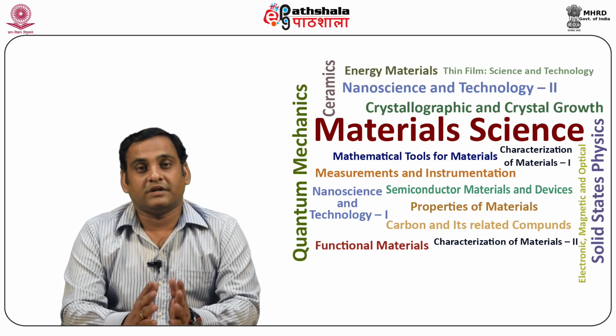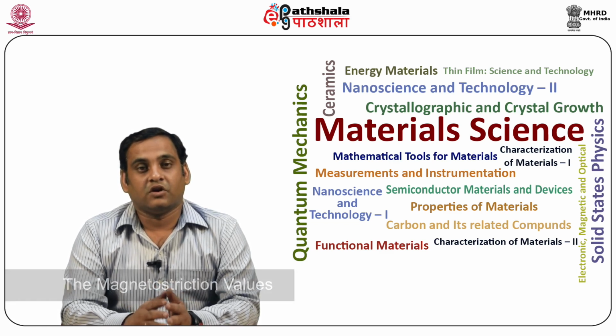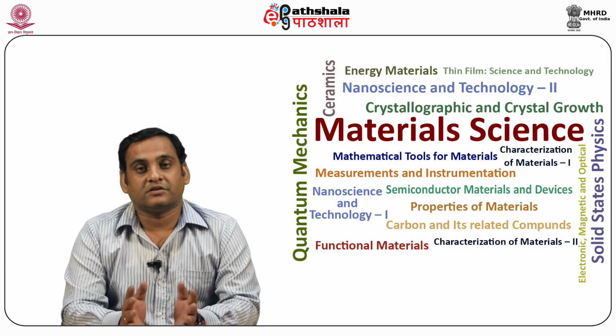If this ideal demagnetized state is not achieved, equation 3 is invalid and the measured magnetostriction will be larger or smaller than the calculated value. Differences in the magnetostriction values observed by different investigators for the same material are usually due to differences in the demagnetized states of their specimens.